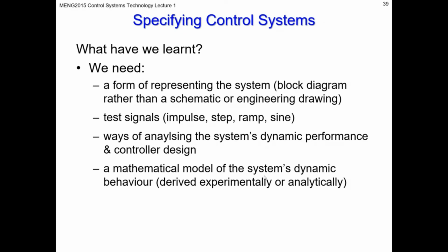To get a model empirically, you measure the behavior of the system by giving it known inputs and measuring its outputs, and by comparing those, you can derive the transfer function, the governing equations of that system, using your experimental data. So there are 2 ways: empirically derived models, or analytical, which bases your modeling effort on first principles.